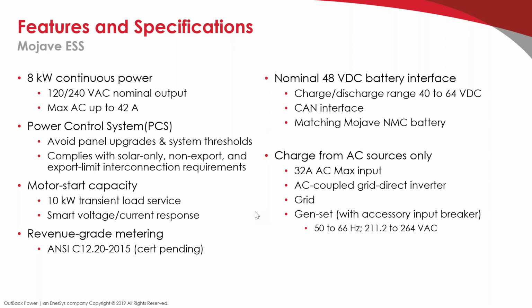So, charging from AC sources. We've got a port in there for a generator. One difference here is that we don't ship with the generator circuit breaker in the system. We found that a lot of people aren't doing generators these days, and so rather than burdening everybody with that cost, we've made that circuit breaker an accessory. It takes about 5 minutes to wire it in.